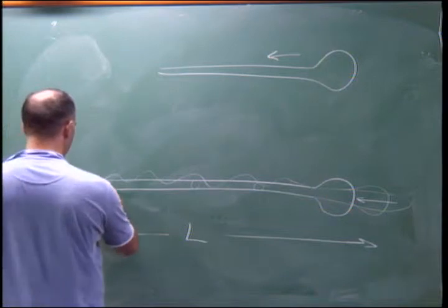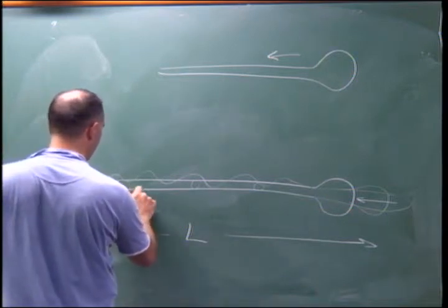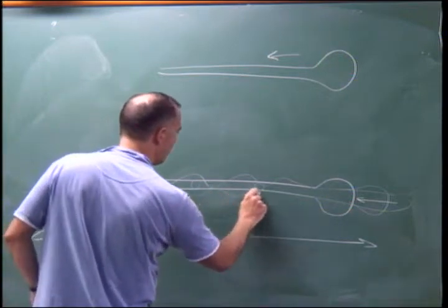The retraction has to be faster than the time it takes for the Rayleigh instability to break the filament. Right, so you want to compare the two time scales. So when does a fiber retract into a single drop, and when does it break up into many?